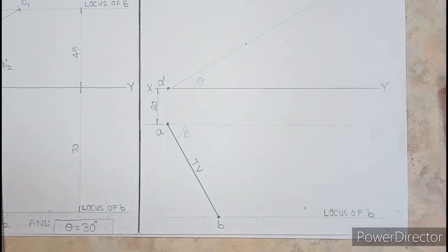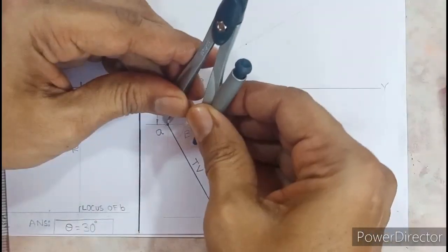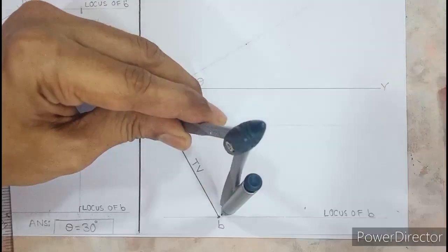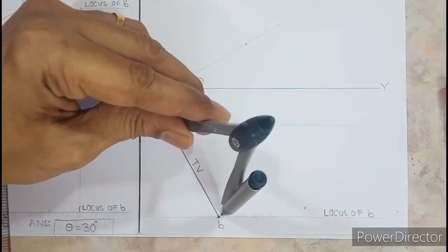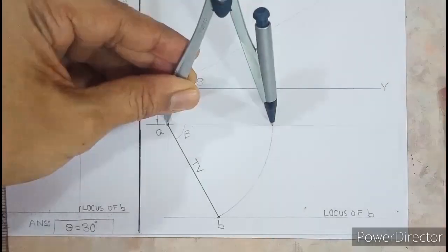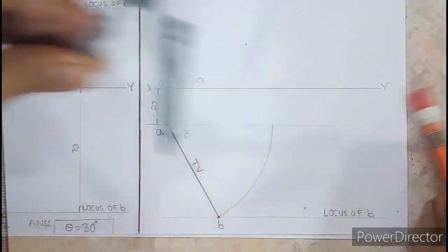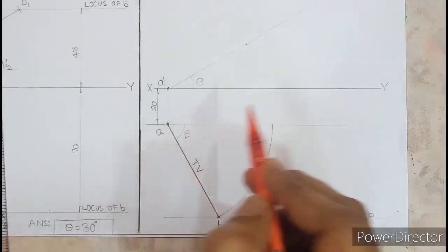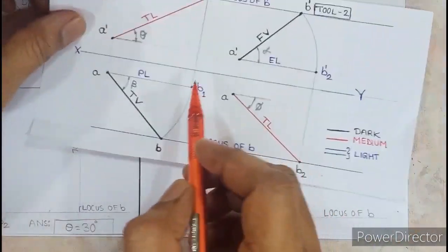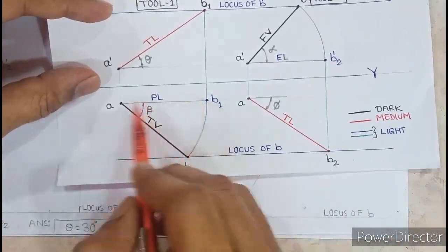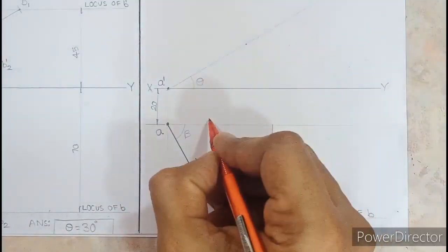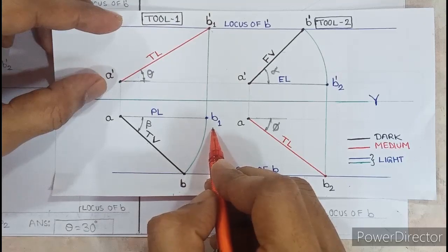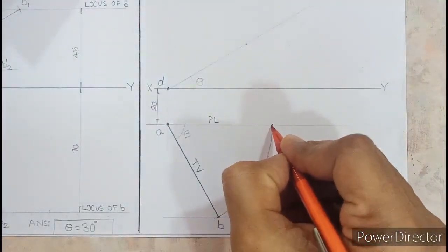So let's start. We'll take this top view in the compass. I hope all of you can see. Rotate this how much? Till the level of A, the correct word to use is level of A. Once you get this level, name this line. So this line is called the plan length, PL. Name this as PL. Name the point B1. So this point is called B1.